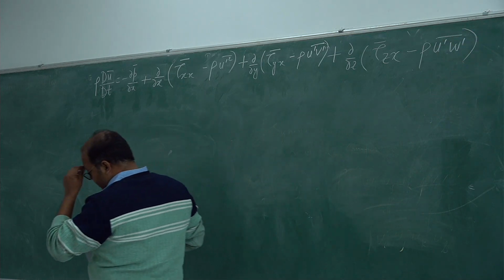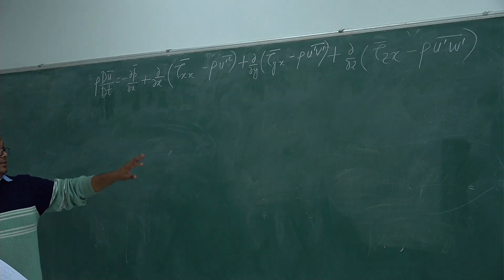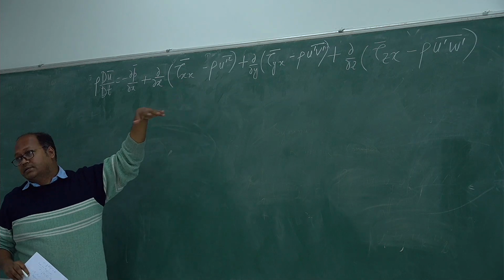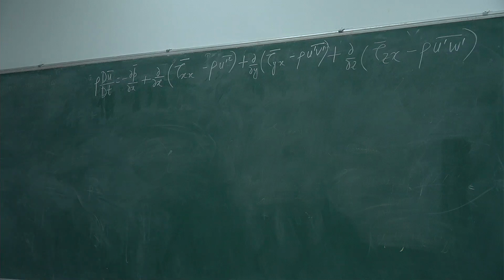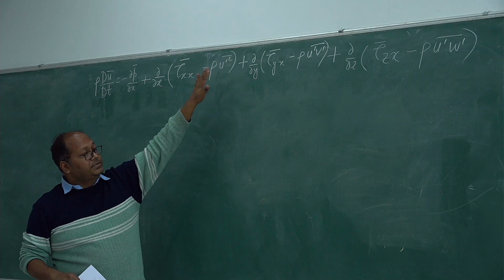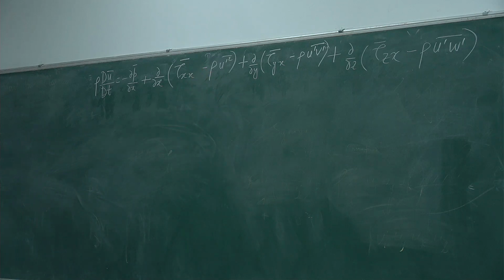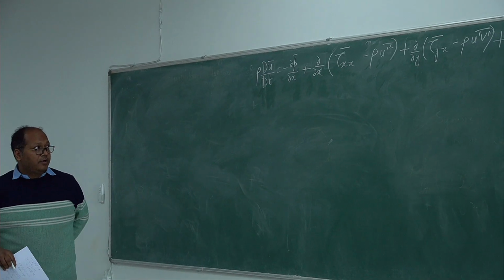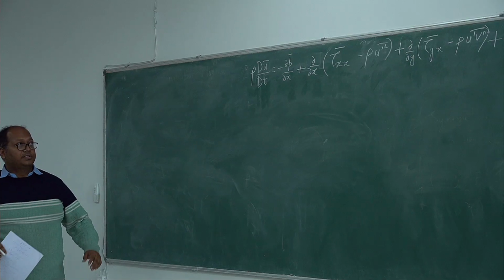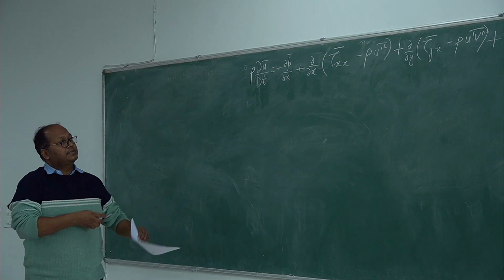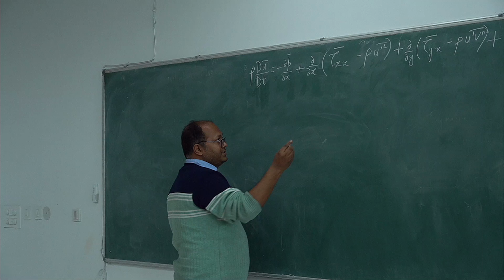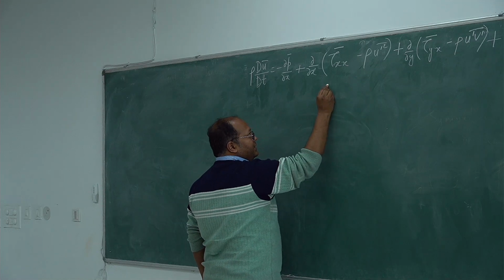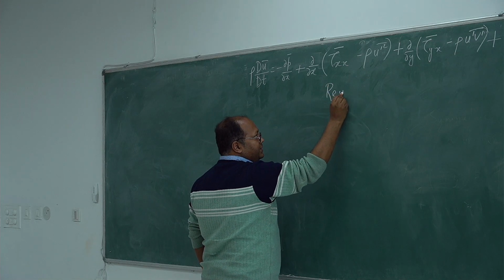And then we said that this tau capital xx involves the velocity gradients, or the mean velocity gradients rather, and these are the terms which are arising because of the momentum flux due to the fluctuating components. These are actually not stresses. However, when Reynolds did the decomposition and rearranged this, just to honor his name, these components are the Reynolds stress,